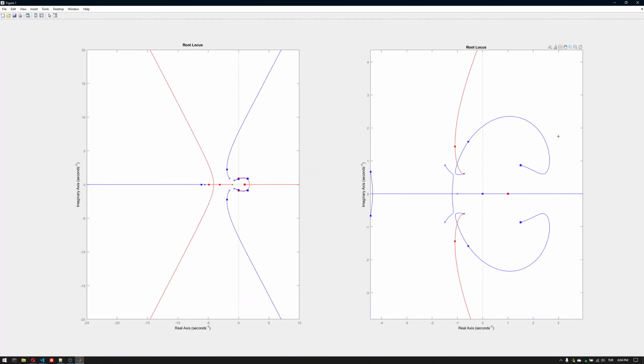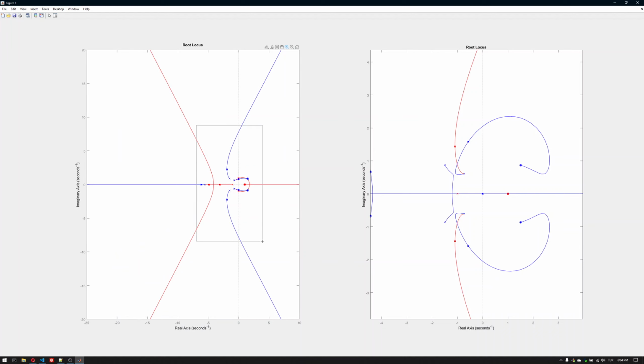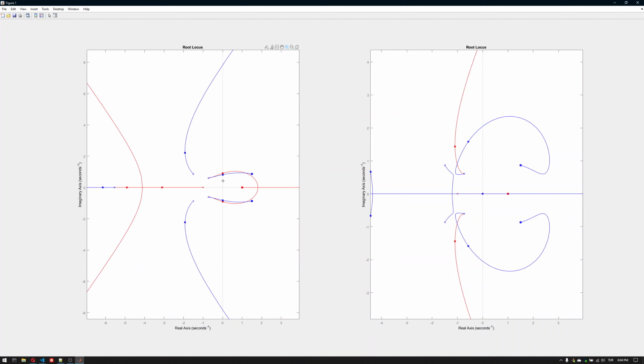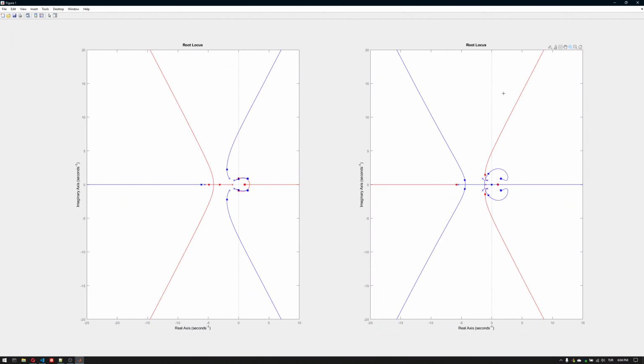There will be a transition or a crossing between each set of pole and zero sets, and this is exactly what's happening here. We have one crossing for the red one here, whereas two crossings appear for the blue one here. It's the same for here, there are two crossings. So the higher the Padé approximation order goes up, the more crossings will appear here.